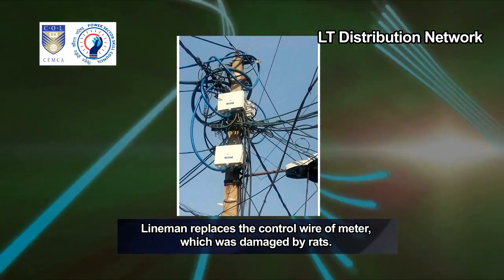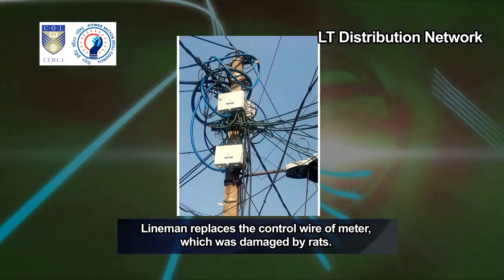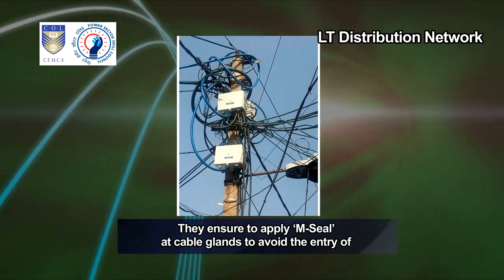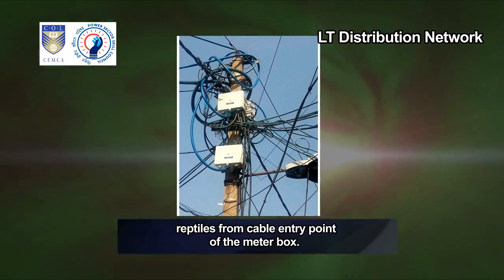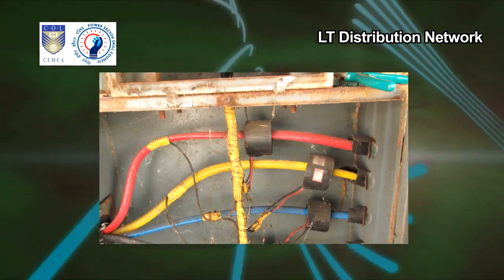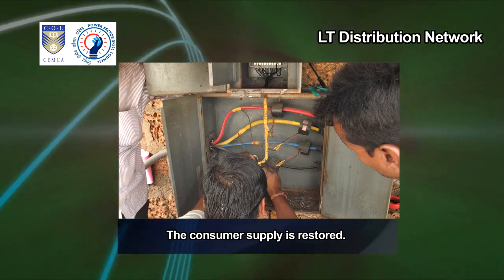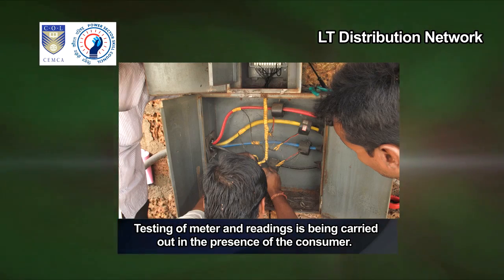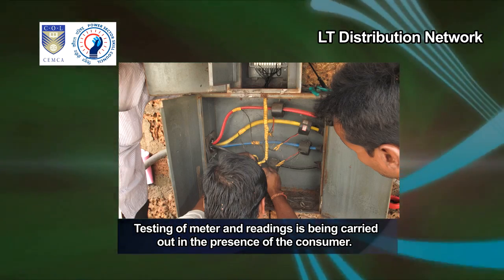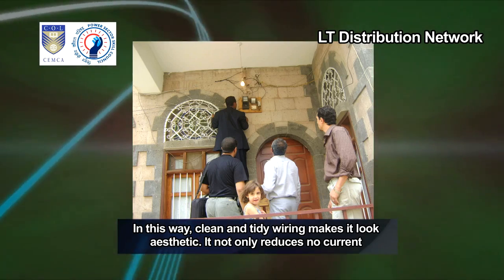Lineman replaces the control wire of the meter, which was damaged by rats. They ensure to apply M-seal at cable glands to avoid the entry of reptiles from the cable entry point of the meter box. The consumer supply is restored. Testing of the meter and readings is being carried out in the presence of the consumer. In this way, clean and tidy wiring makes it look aesthetic.